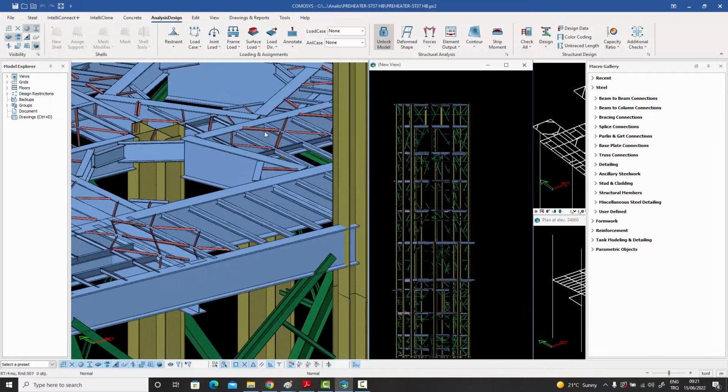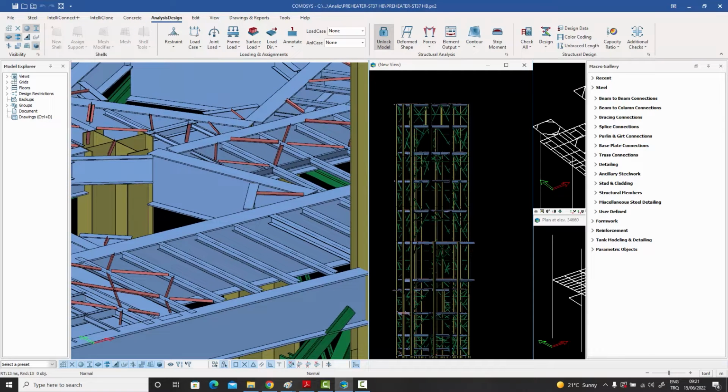There you have a case in which you don't want to design according to the capacity of the beam, and like we all know, floor beams are typically not connected in moment resisting way, but they're hinged connections. So the primary forces in most cases are your V22, the vertical shear at the ends of the beams. And in some cases, there might be some V33 as well. And in some cases, there might be some axial load in the beams as well.